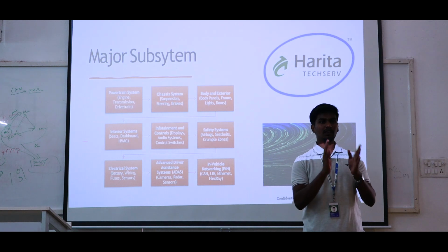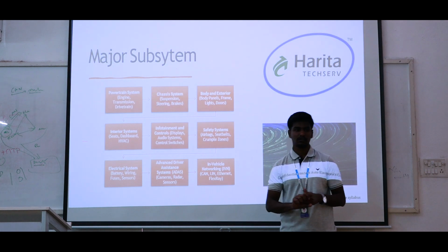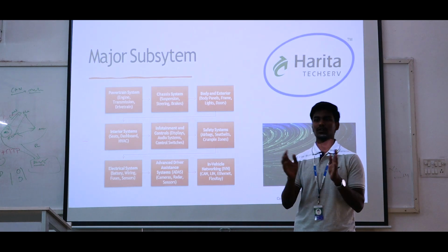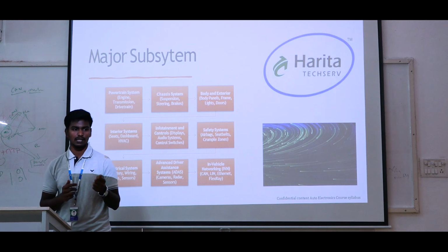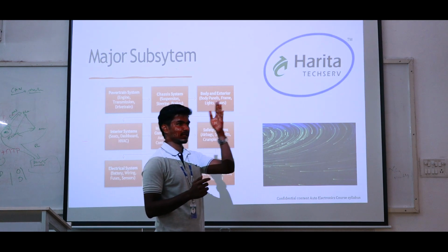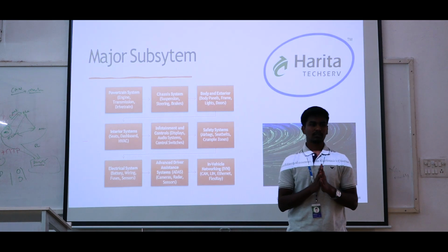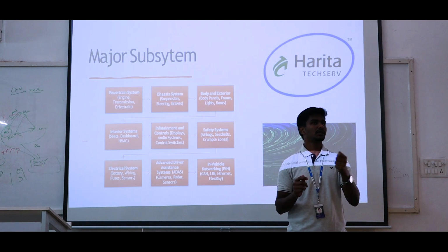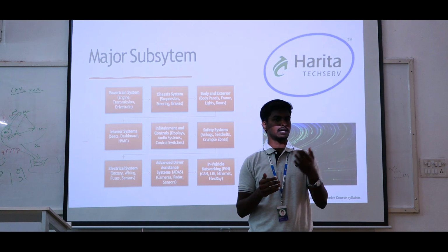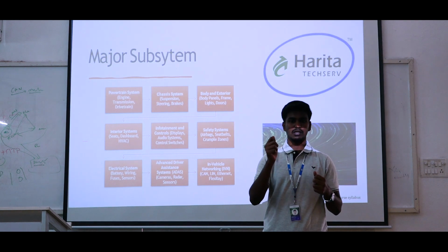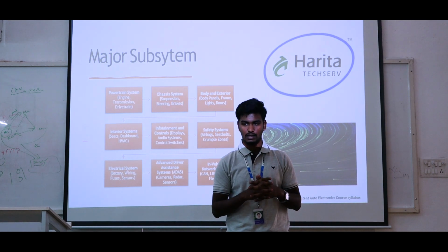In automotive electronics, in-vehicle networking majorly covers CAN, LIN, Ethernet, FlexRay. LIN is used for short-line communication. For example, pressing a button gives an immediate action, like turning on a switch turns on a light. But the CAN protocol is not like that. We can use wiring up to 2.8 kilometers and get the same data speed. For example, if you send a vehicle speed of 200, the speed will be 1 Mb per second over the 2.8 kilometer wiring range.